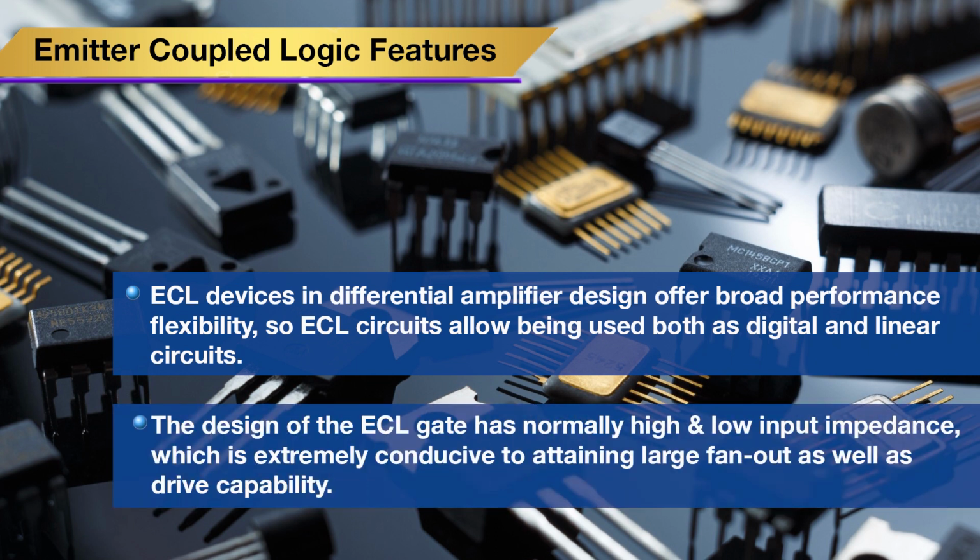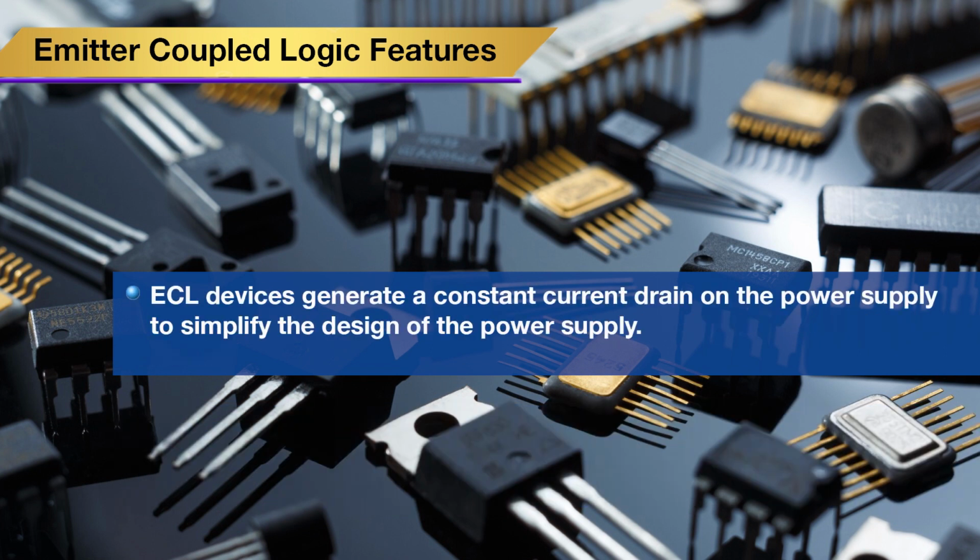The design of the ECL gate has high input impedance and low output impedance, which is extremely conducive to attaining large fan out as well as drive capability. ECL devices generate a constant current drain on the power supply, which simplifies the design of the power supply.